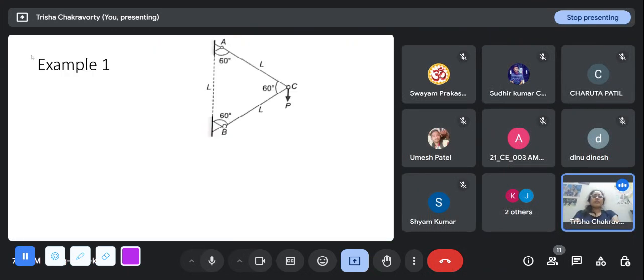So this is a truss with a hinge here and a hinge here. It has two members. Remember when we were looking at stability of trusses, we had seen one criterion, that a truss must form triangles with its members. So you can say that this does not actually form a triangle because it is just two members here.